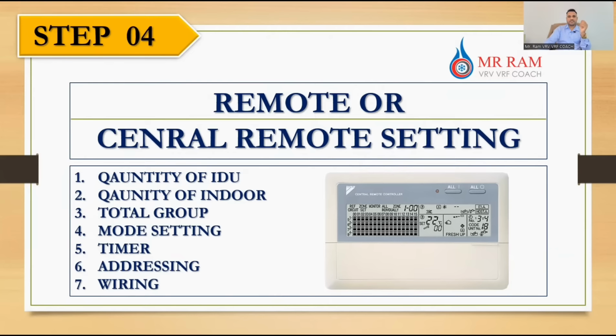About the timer also, sometimes the timer is set in the individual indoor unit thermostat, so automatically the indoor unit blower motor and expansion valve are closed and the cooling effect is not coming. So dear friends, we have to know all about the timer. There may be no timer, or there may be a lock. And after that, the addressing should be perfect in the indoor unit and central control everywhere.